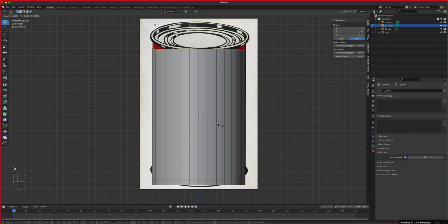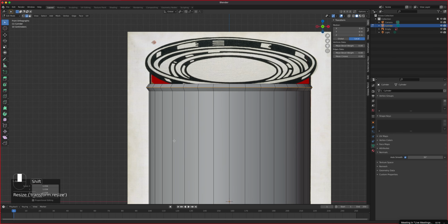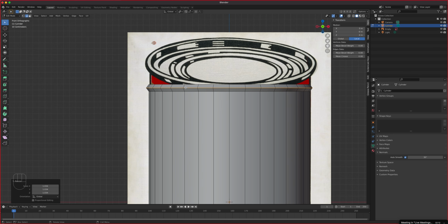right now. If I press S, they both start scaling from the center point, right? So if you remember the boombox, we did something with this so that it doesn't scale from the center. They need to scale with their own selection. So we have to change what used to be the median pivot point; we're going to go with individual origins just for this one. Okay, so I'm going to hit individual origins, press S, and then scale out, sorry. So it kind of looks like it protruded a little bit like that. Okay, that's what it looks like. And both top and bottom are still selected.